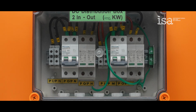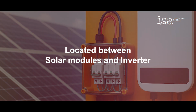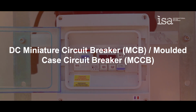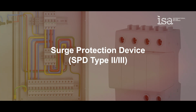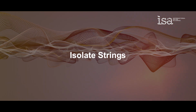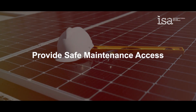DC distribution box, DC-DB. Located between solar modules and inverter, the DC distribution box protects the DC side. It typically includes DC fuses, DC MCB/MCCB, surge protection device, SPD Type 2/3, DC isolator, monitoring equipment. Purpose: isolate strings, protect inverter from surges or faults, provide safe maintenance access.